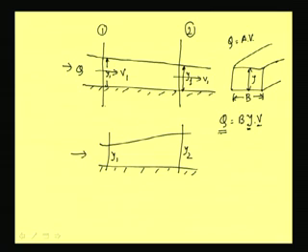If the same amount of discharge is coming, and no discharge is entering the channel portion laterally, it will continue to move, and the velocity here will be v1 but the velocity here will be v2, a different velocity, because the depth is changing, that is, the sectional area is changing. So this sort of flow we refer to as non-uniform flow.